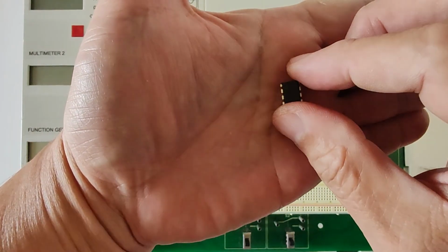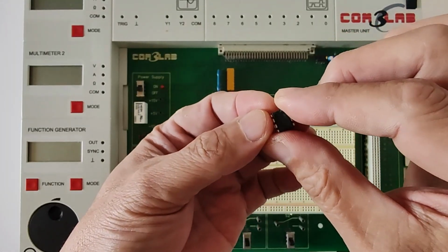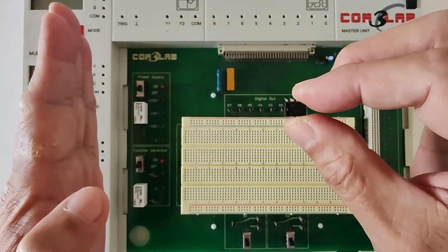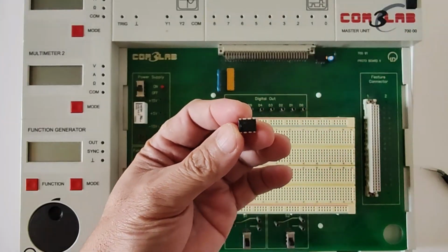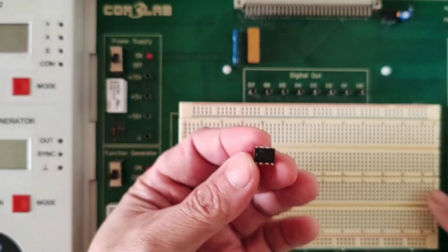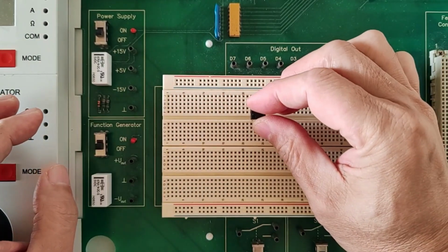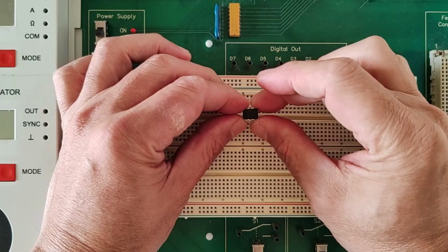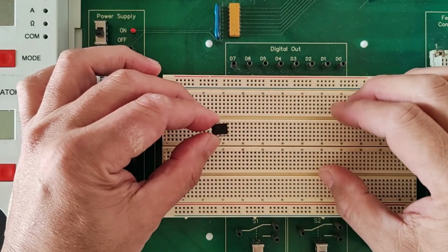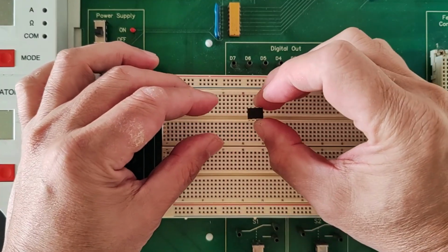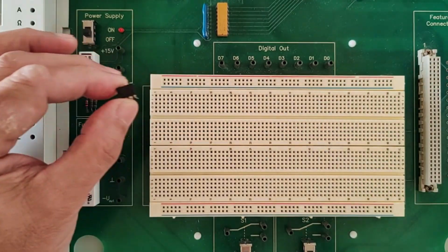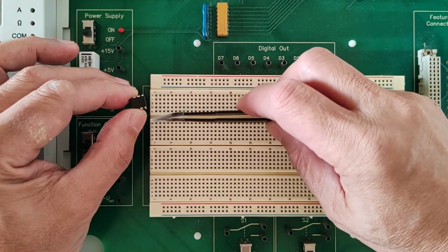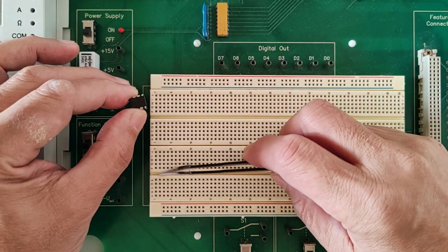Now what I will do is connect the LM741 to the breadboard in that manner, wherein the notch is facing here on the left side. Now, my advice is this. Try to find a place on the board wherein the IC or your 741 will snug fit. Because if the IC is loose, you will not get any output waveform. There are a lot of places here anyway. So you put the 741, the integrated circuit, on the gaps here. You have two on this board. One is here, the other one is here.